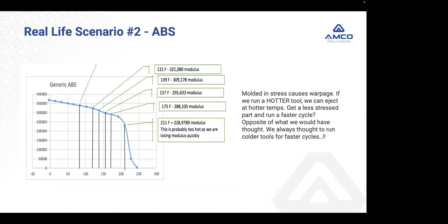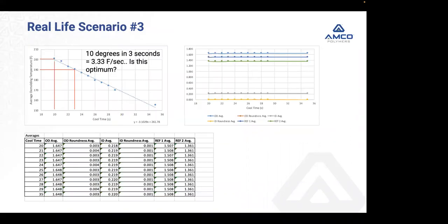I was working with Mr. Seppi, and he told me one of the things with annealing parts to relieve stress is people cool the plastic too quickly after they anneal. He said, you want a nice slow heating. So another advantage of this demolding temperature is kicking my part out. I pull out, let's say maybe a degree a second, and that's probably pushing it a little bit.